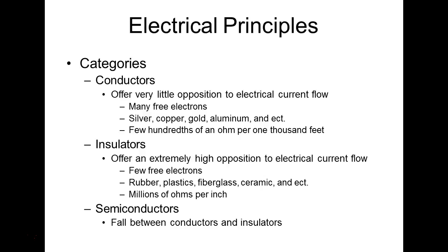But we do have a special meter I'll bring called a megohmmeter. And that meter's set up to measure in what? Megohms. So we'll bring this out and we'll actually measure the resistance of the insulator. We'll take one lead and clamp it onto the conductor. We'll take the other lead and clamp it onto the insulator. And we'll crank that puppy up. And it puts out a real high voltage. I think ours puts out like 600 volts. So don't put your fingers across it, even though it doesn't have any current available.